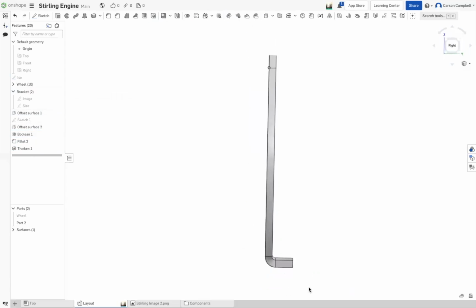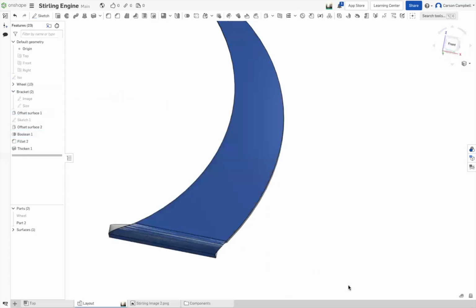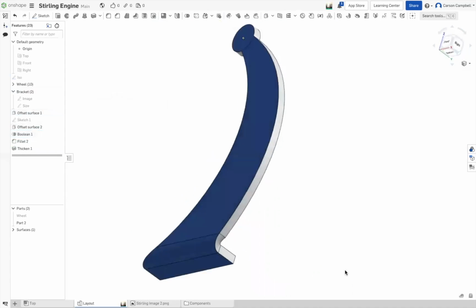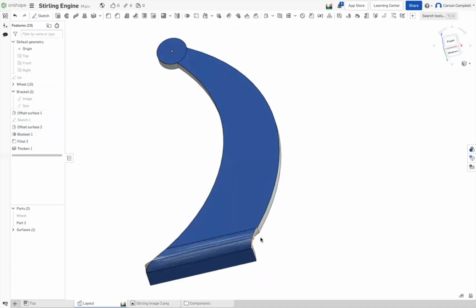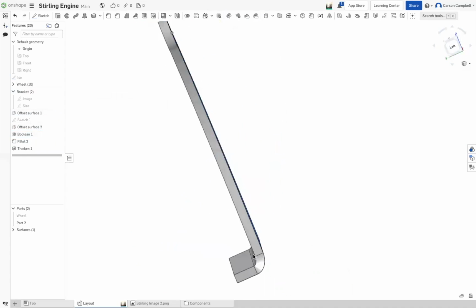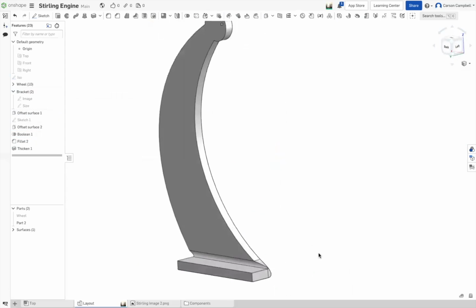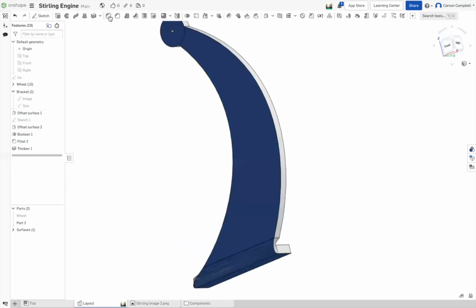But okay, so there's your sheet metal part. It's not a sheet metal part though. That is just surfaces that have been thickened. Oh yeah, that looks weird. Okay, so go up to fillet and delete that and delete the thicken. Nope. Oh, sorry. Feature tree. Pick that, delete.